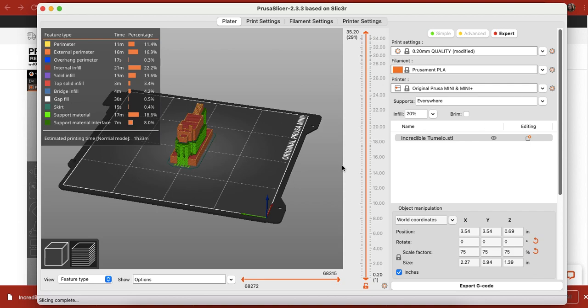So other things to go ahead and keep in mind is that if you do have a G-code, you can't modify a G-code, so you do want to have it saved. You can only modify an STL. The G-code itself is unfortunately something that you can't modify, but you do want to make sure you have a copy with it in case you do need to do duplications, things of that nature.